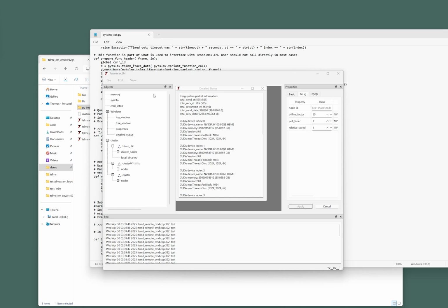Okay, I'm going to be doing another demo, and this time I'm going to show using a cloud node with 8 GPUs to do a simulation of a directional coupler as well as a mode solve. You may want to take a look at my previous demo where I used a remote compute node. The setup here was exactly the same, with the one exception that this time I used a cloud node. But just like before, I SSH'd in, I copied over the binary package and then untarred it and started up the utility, and then I connected to it.